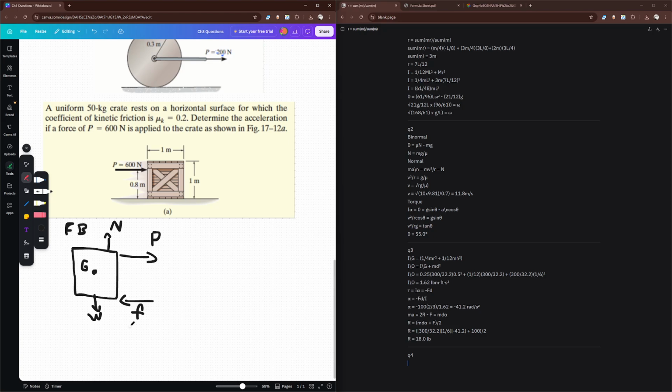If the normal force was right in line with the center of gravity, we would have tipping, because our moment would be this force. So we'd have a torque from this force, and we have a torque from the friction. And since it's kinetic friction, the force is obviously causing movement, right? So if it's causing movement, and the friction just counters it a little, that would cause this to tip like so. But we know that it's not going to tip, which is why the normal force is offset by some distance here. We need to get this distance, of course. And then obviously the kinetic diagram is just like this, MA. That's our kinetic diagram.